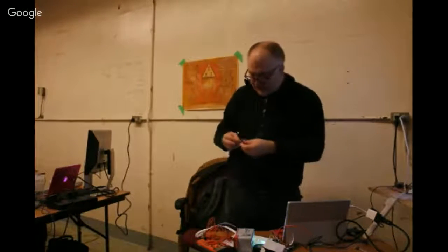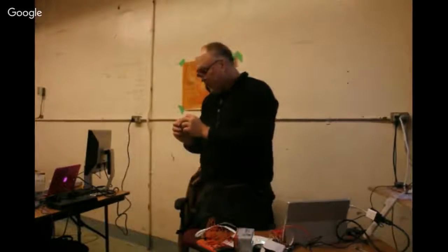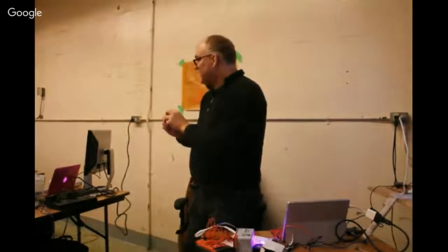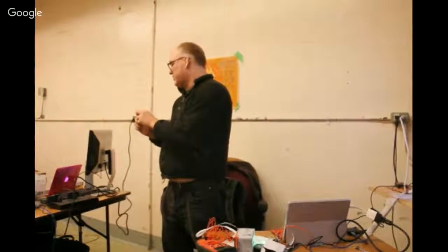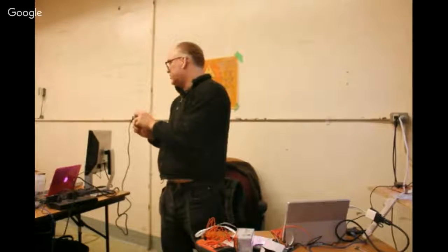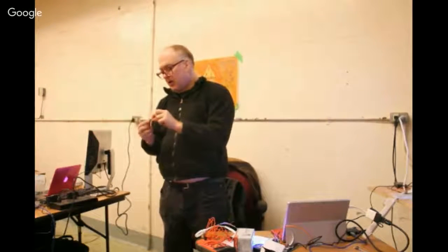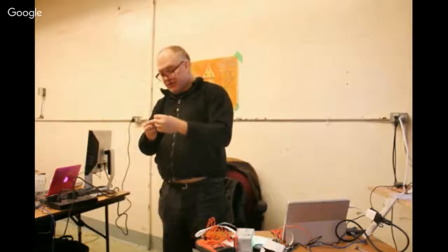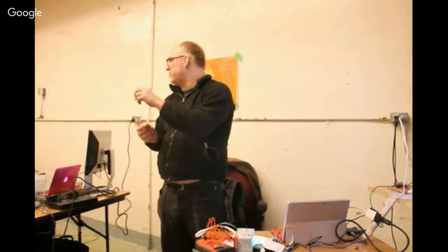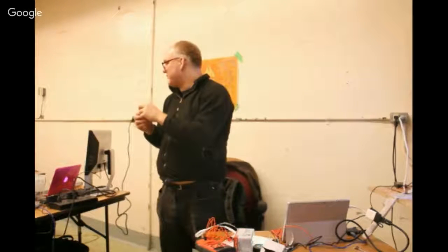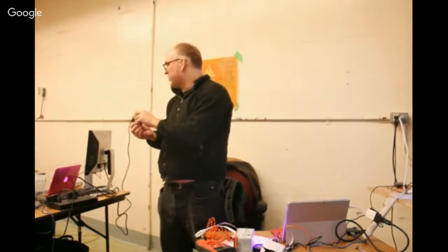Looking at the transistor, we've got the ground pin, and the center pin, where the current is going to flow between the center pin and the ground pin. And then the signal goes in on the left side pin. The ST is what I remember as signal on this particular pin package, because it's labeled ST for the manufacturer of this particular transistor.